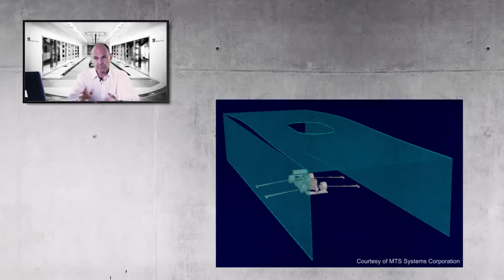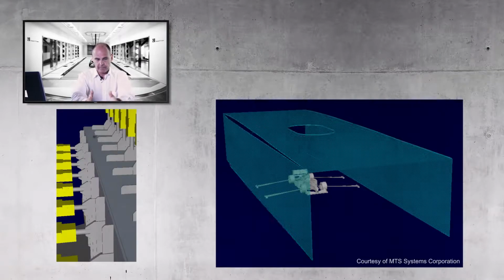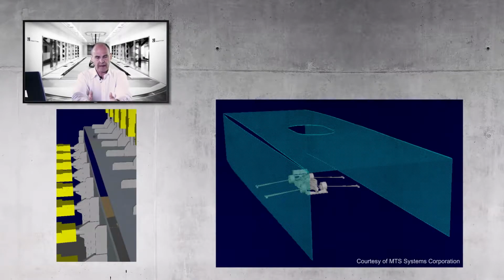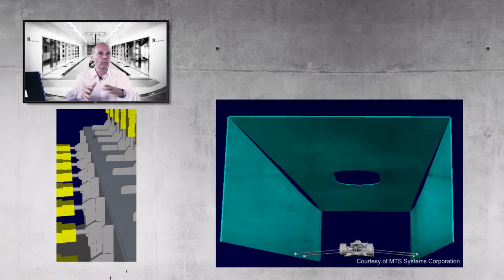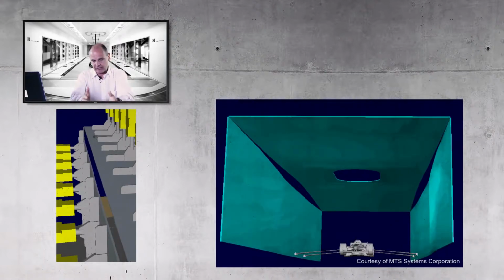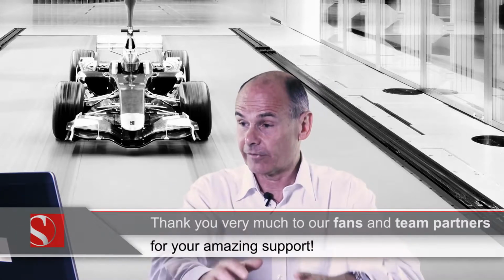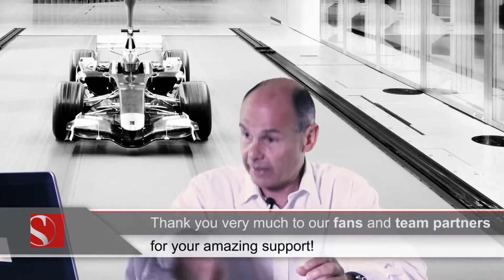So a contoured wall is not commonly used, but adaptive wall is used quite a bit in motorsport and is a really clever technology, and basically in a very simple way allows for the blockage effect without quite worrying so much about the exact shape. We don't use that technology in our tunnel, but it's a really good technology and allows a team potentially, or a wind tunnel manufacturer, to make a slightly smaller wind tunnel and use this technology to correct for blockage, rather than just make a nice big one so the blockage correction is smaller. And that's the fundamentals, if you like, of the design of a wind tunnel.